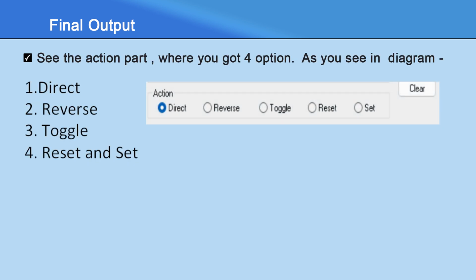Okay. So, here I have selected the discrete value for the touch push buttons. Here you can choose the discrete value, action, show window, hide window. Here I have selected the discrete value. When you select the discrete value, you will also be asked to add the tag name. For this you have to add whatever tag name you want.